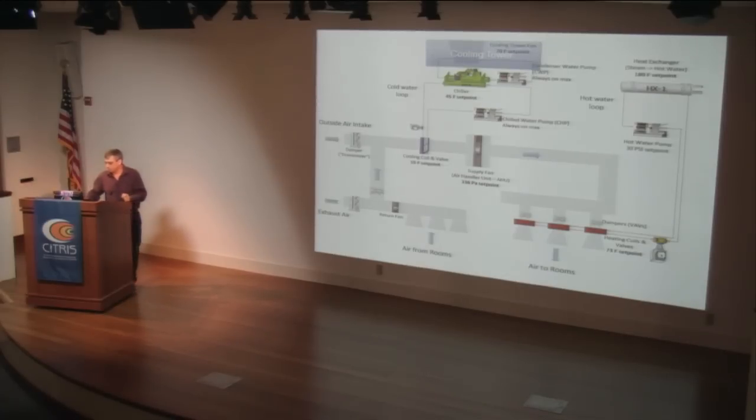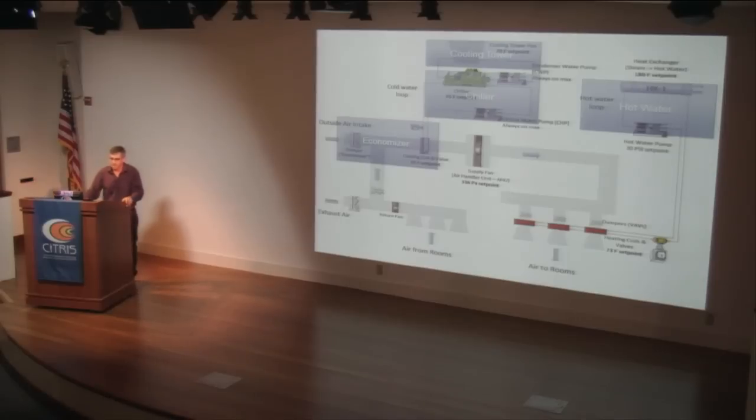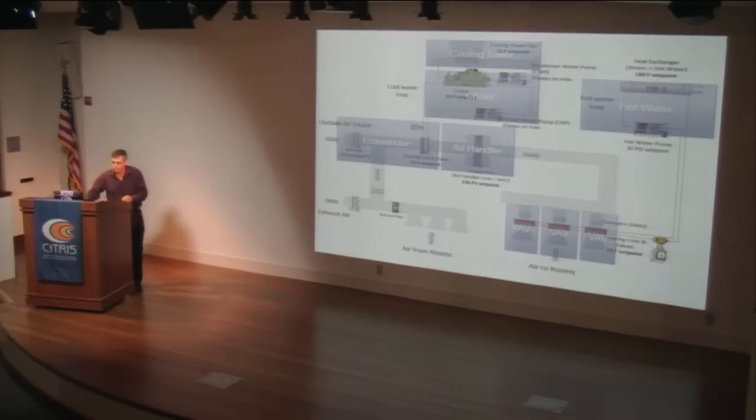So think about the cooling tower loop talking to the chiller loop through the water that got chilled, as well as the hot water loop, the economizer, which is a different kind of loop, mixing fresh air with conditioned air, the various air handler loops maintaining the supply and return fans. Each and every one of the 140 VAVs is its own control loop. All of these are busy doing their thing relative typically to a small family of set points. Okay? And you've seen a taste of some of the behavior. It is a marvelous thing that these things work at all.